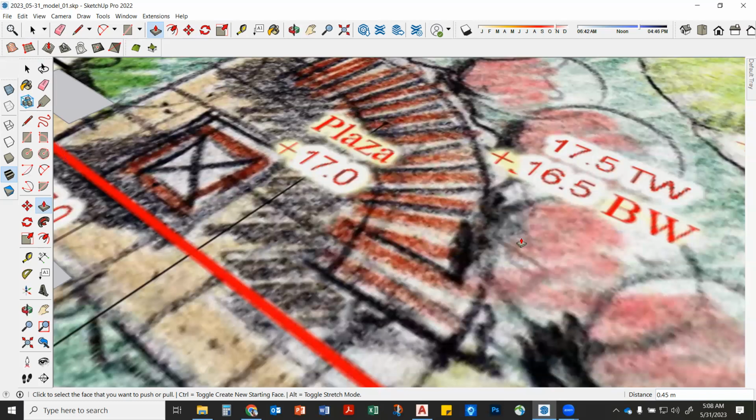Hey guys, listen real quick, pause. So here's our plaza, right? So we have a retaining wall that's doing this, yeah? Or we have a seat wall doing that, right? This is 450, right? But then what it's saying, this elevation is at what, 17, right? This is at 17.45, right? It said 50, but we changed it because we want to be more accurate, right? Then our bottom wall is over here at what? 16.5. Okay, does that make sense?